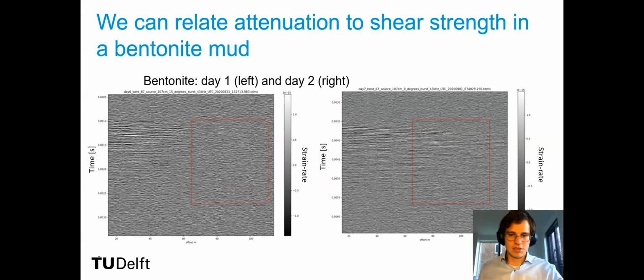So we went originally along the same type of approach as Zack did, with the goal of characterizing the shallow shear wave velocity using a cross-correlation based approach, where we calculated cross-correlation virtual source gathers, performed a wavefield transformation, and then took those dispersion measurements and inverted them for a sediment profile. But not all of the source locations worked quite as well. In particular, in this end of the cable where there are all of these additional high frequency Scholte wave peaks present,